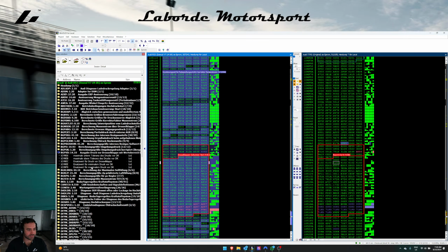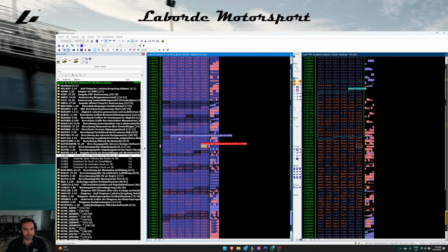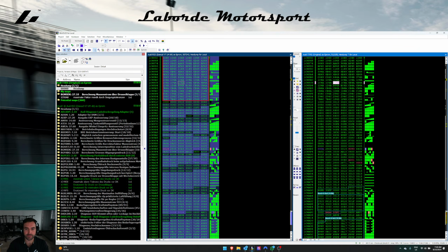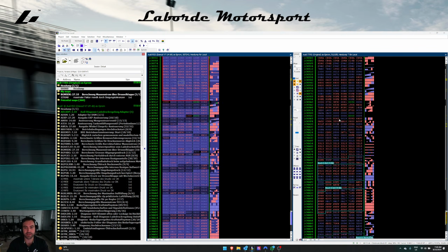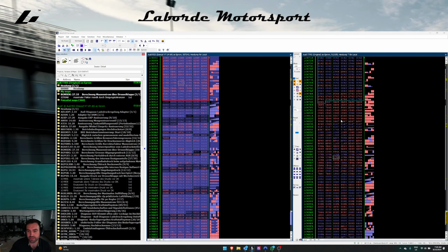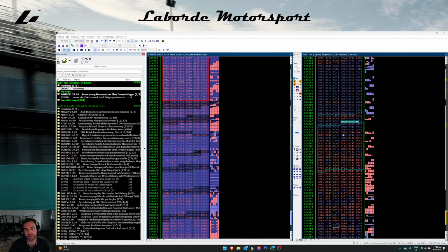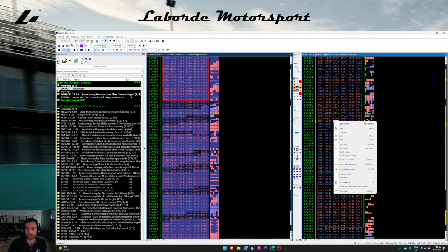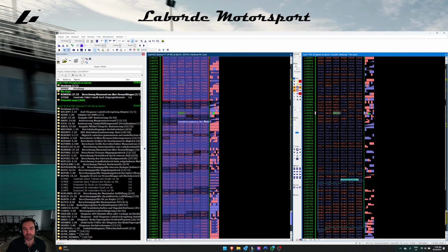The idea is to go through the maps and look at the parameters that we need, and then search for them between the two files. The way that I search for it is I select a bit of data on the left, and then I can match it up with the window on the right-hand side. If I offset these, you'll notice it's color coded in red, blue and green. Green indicates data is matching between the two software versions on the left and right-hand side.